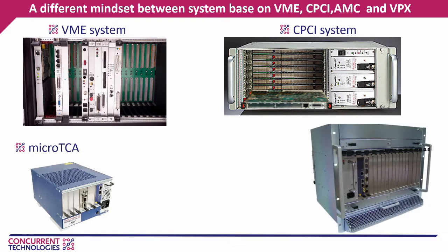So an example is micro TCA. Although micro TCA is point-to-point, it still is fairly easy to use because everything has been frozen and defined such that all the slots connect to a central switch called the MCH, and there is very limited I/O also defined with micro TCA.